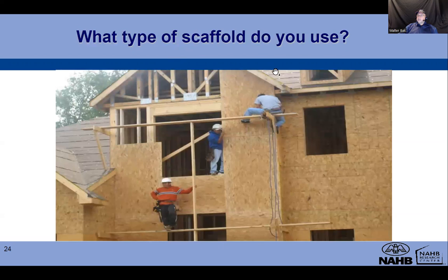What else do we have? What type of scaffolds do you use? Here is a picture that I inherited from the previous years. Can you identify the parts? Is there a stairway there? No. Is there a ladder? No. Is there a toe board? No. Is there a mesh? No. Do the platforms extend 6 inches at least? Yes. Well, that's one thing that's correct about that, but it's about it.